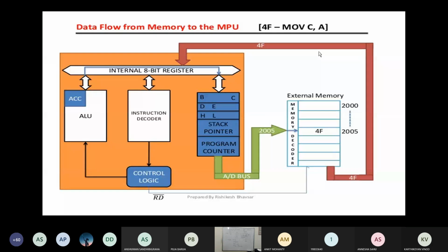Please try to understand. This is the small parallel process going on here. When the instruction is being decoded, program counter has no role. So the control signal will already indicate the program counter to go to the next location. That's how the instructions will be worked out sequentially, one after another. The program will never be executed randomly. It's always in the sequential mode. Now I think you should be having doubts. Please open up.